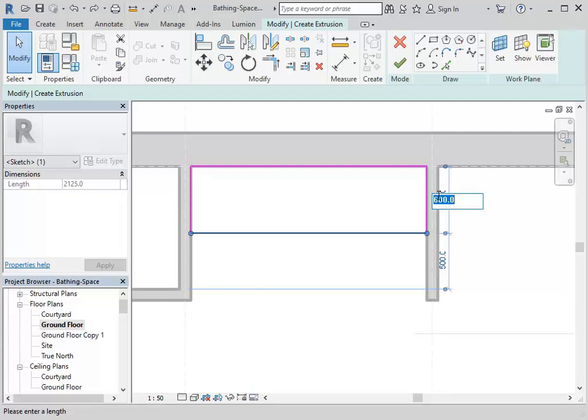550 is what they'll tell you in the catalogues you can go down to, and some units are made for that, but it's not safe to do that because things like dishwashers and fridges that are made for kitchen benches usually are at least 600. They don't usually go down to 550. Even though I know they'll tell you in the kitchen catalogues you can do 550 or 560, 600 is much safer. So that's a good starting point.